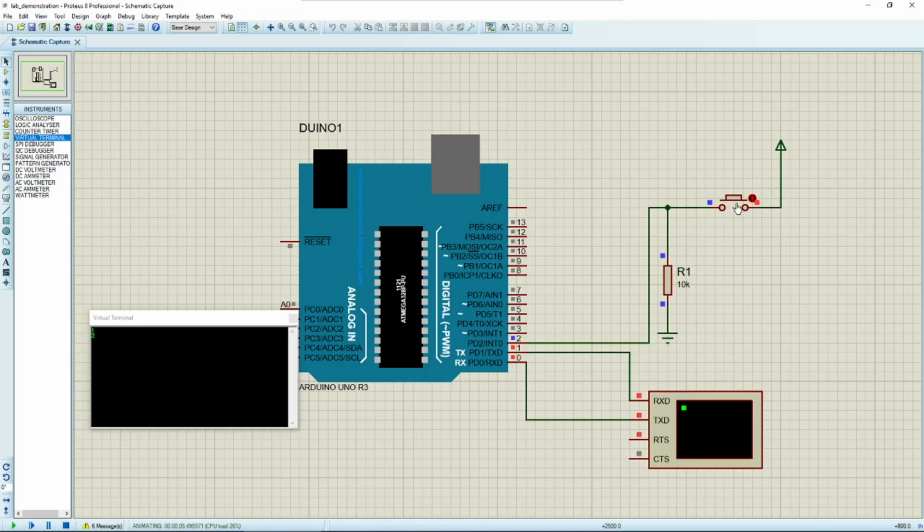I am showing you again. I just pressed it, so just pressing it counted to 3, and if I release it will count again. So now 3 to 4. I just clicked, so it counted 5, and then release counted 6, because it is sensitive to the change in value. So I am just changing. If I make it like this, it just counted 1.